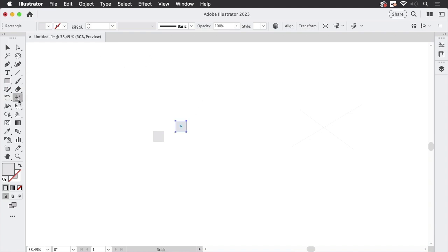smart guides. And let's take the scale tool, and you see when I scale like this, I get some help because the width is the same now, but now it also tells me I have a proportional scaling. And these tools somewhat interfere with pressing the shift key. So sometimes you get some weird behavior of Illustrator when you use the shift key together with smart guides, and that's caused by this. It's kind of a pity, but that's the way it works right now at the moment.